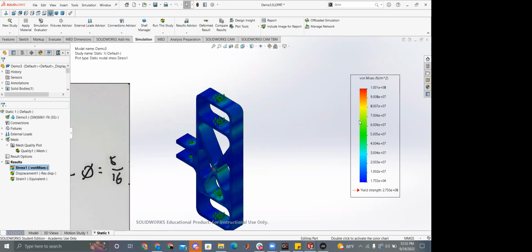We've talked about this bar before. The top is the maximum stress. The bottom is the minimum stress present in the model. Yield strength is the stress at which your metal will fail and start to deform permanently. So of course we want the maximum to be lower than the yield and the fraction by which it's lower. So if you divide the yield by the maximum, you get the safety factor, which is by how much your material won't fail given your loads.